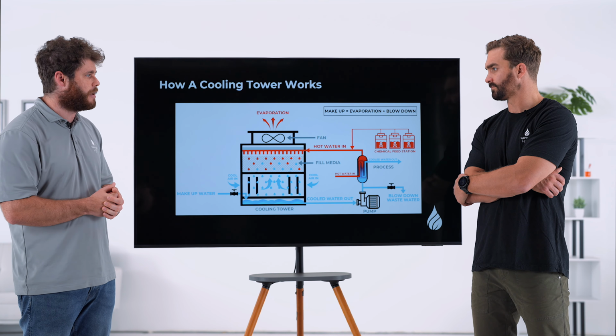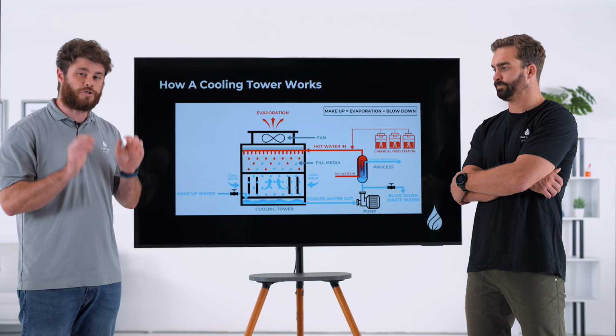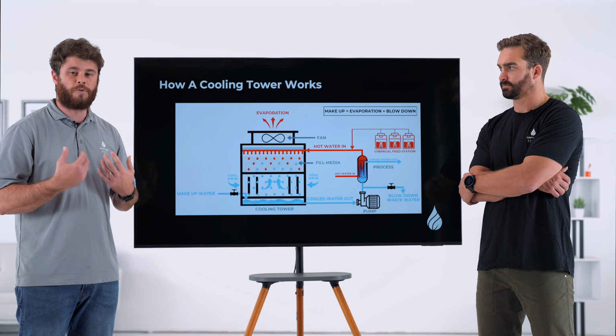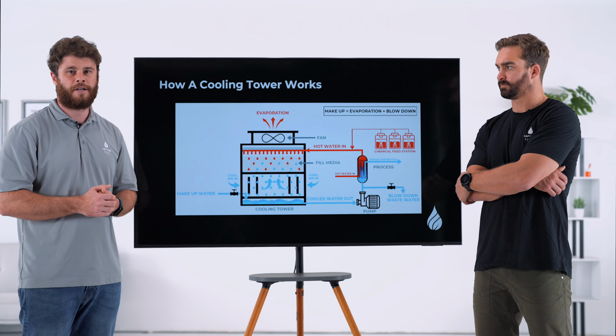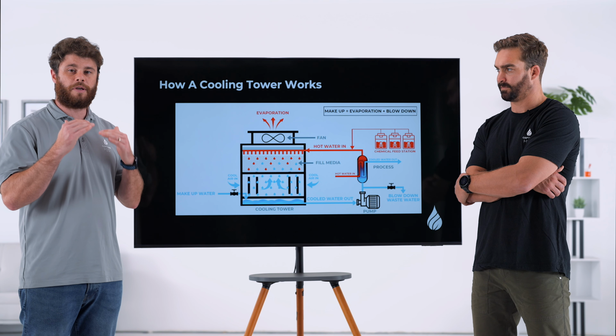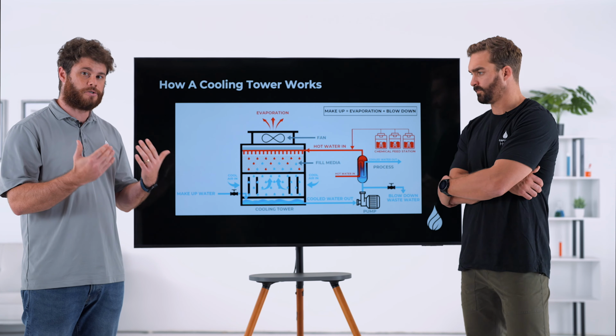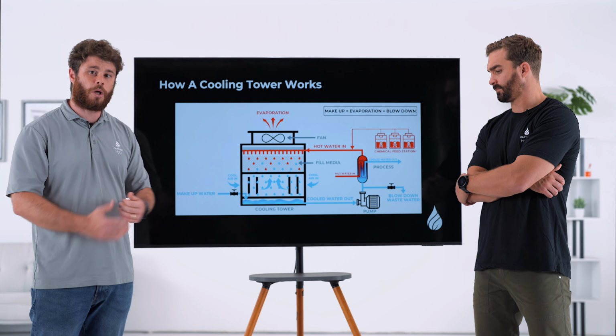And the status quo way to address these issues is what you see in the top right corner of this slide, a chemical feed station. We're dosing the system with chemicals to protect the equipment from those increased mineral concentrations. The problem this presents is the chemicals are only able to protect your system up to a certain mineral concentration. When it becomes too dense and too saturated, your system is going to start being at risk of scale, corrosion, and bacteria. When we hit that threshold of mineral concentration to protect your system, you initiate what's known as the blowdown process.